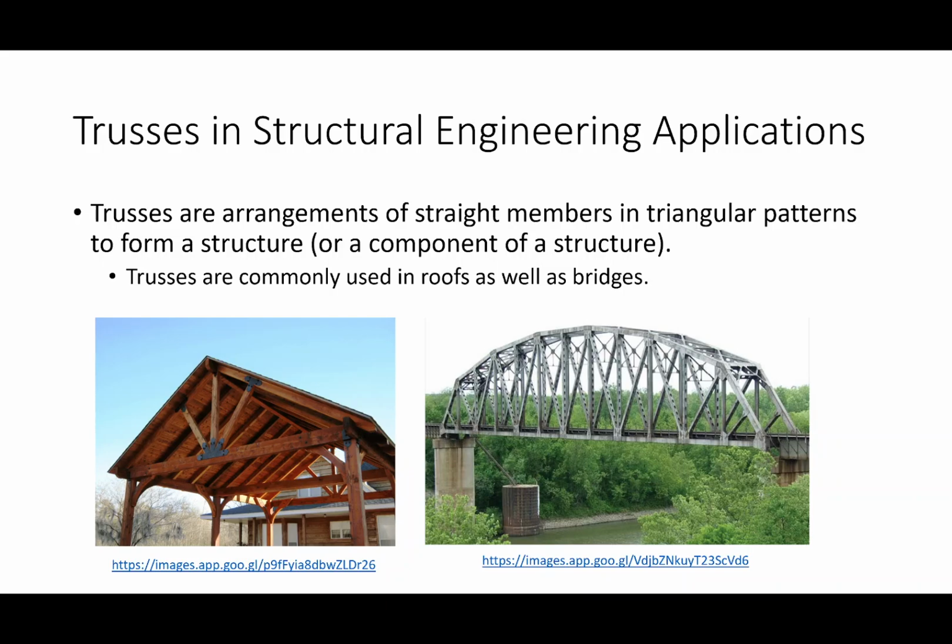The thing about a truss, if we're talking about structural behavior, is that trusses are very stiff. Now, I use that term very specifically. You might think of the term strong and maybe the term stiff as meaning the same thing. They don't. Strength and stiffness have very specific meanings in the land of structural engineering.